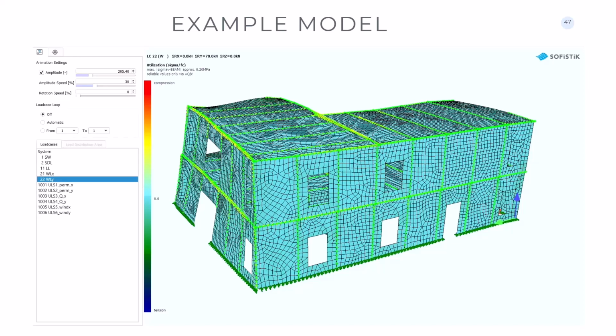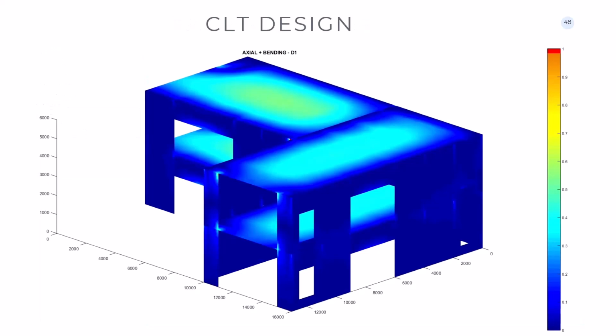You see, when you apply the wind, you can read how deformable this building is with respect to a corresponding concrete building, for example, and how important this deformability is, because it brings the loads in a completely different pattern with respect to other, more standard construction materials. And when we apply the procedure, we are able to post-process all the formulas that I was showing before about stresses, and plot for each formula, or for a group of formulas.